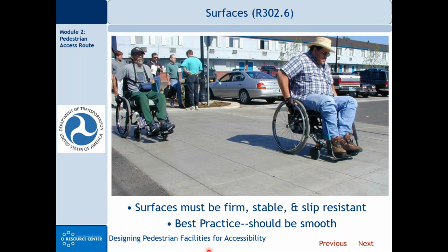But surfaces like grass, I think we talked about that yesterday. Grass is not an accessible surface. Bare earth, a mulch surface, stone, those are not accessible surfaces because they are not continuously firm and stable. You know, I guess now maybe a grass surface here in Morgantown for the last 2 weeks might be firm and stable because the ground is frozen so solid. But you know, come the warm up that will certainly come, that ice is going to melt, soil is going to kind of become muddy, and so it's definitely not going to be a firm and stable surface all the time.